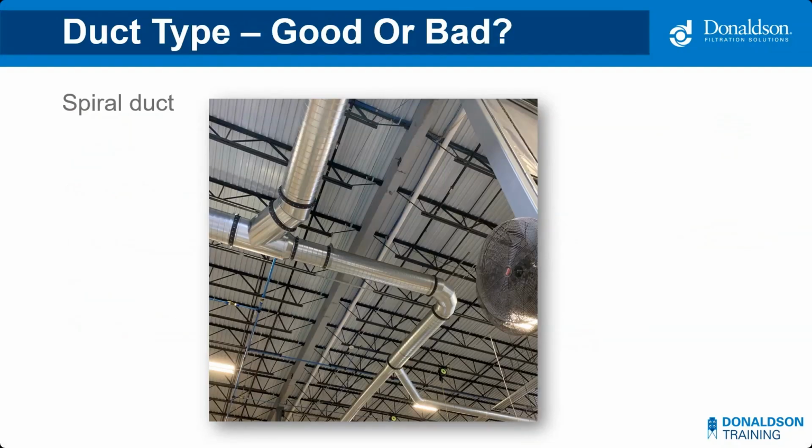It looks like we got a few mixed results. There was a little bit of a delay in answering that one, so a little bit more of some question here, I think. No, it actually is very common to be a hot topic here, whether it's good or bad. Spiral duct is less expensive, and although I've seen it used effectively, it can leak air and could impact your design airflow by as much as 10%.